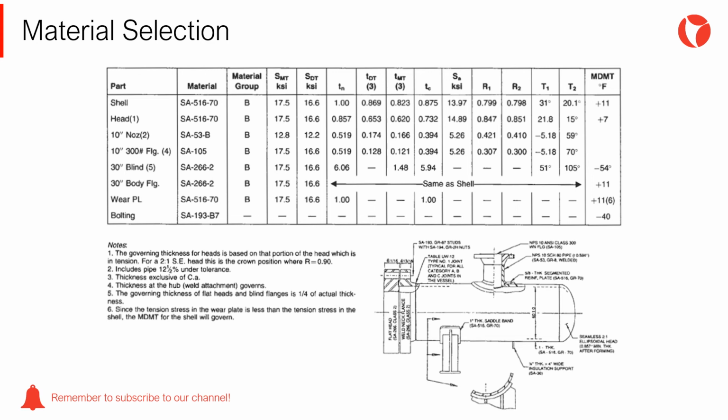It should be noted that to determine the MDMT of a pressure vessel, it is necessary to obtain the value of each of the components, later determining the overall value of the equipment with the most restrictive of all the elements or components.